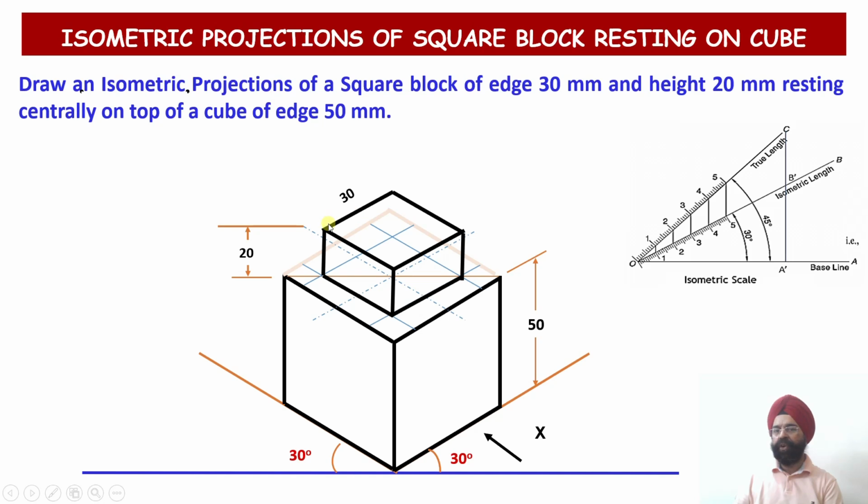Now you can see we have drawn the construction of the square block, in which you can check the base was a square, the top is a square, but the base edges you can see we haven't darkened because these base edges, they have been covered by this face and the top face. So if you consider this to be front, these two edges of the base, they have been covered by front face, side face and the top face. So that is why these two have been just joined by lighter lines or the thinner lines over there.